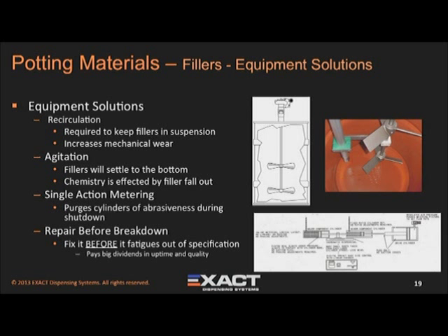When you go to recirculation, you are moving many more gallons of material than you are actually dispensing. You must know the settlement rates to know how much recirculation is needed and how often you circulate to maintain production. All supply tanks must be agitated, but at a rate that does not introduce air into the liquid. The metering systems we like to use at Exact when the material is heavily filled are single acting designs such as that pictured on the bottom of this slide. They allow us to purge the meters when not in use.